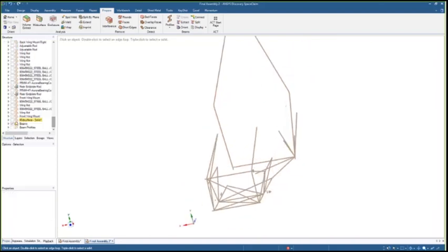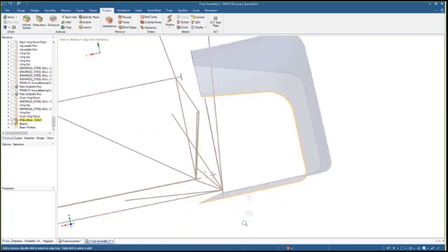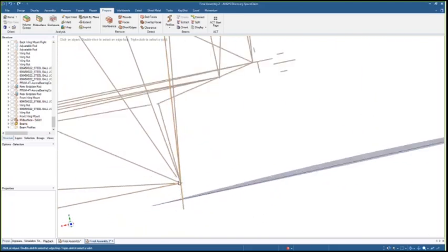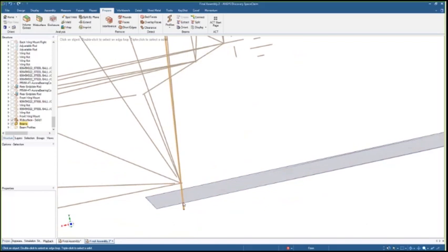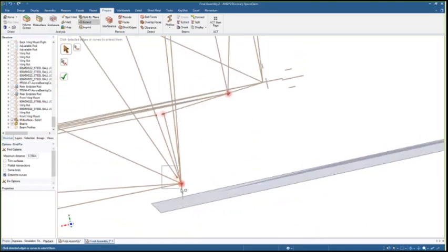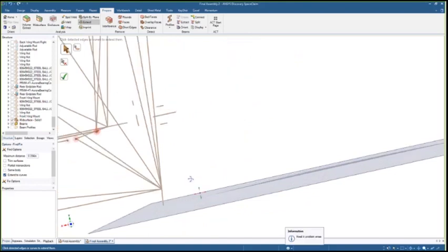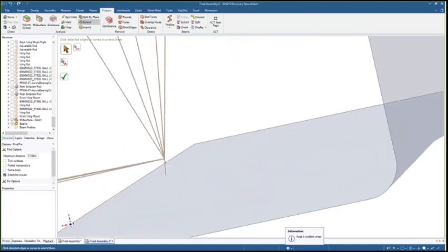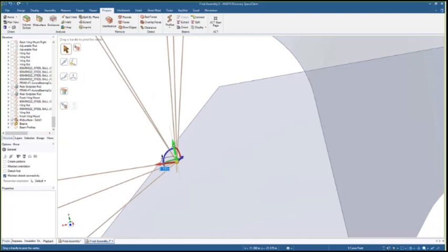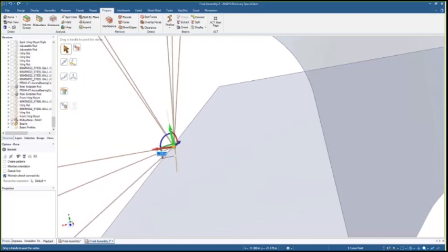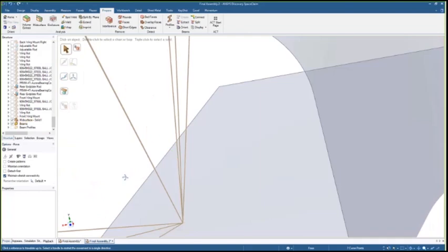And let's just go ahead and show that last mid-surface. So you'll notice that our beam elements are both not connected to each other and not connected to our shell element. But this extend operation does have that ability. Here, it trimmed it back to that surface, and now we could go ahead and extend these to one point. If there should be that connection like here, that's fine. Or, believe it or not, the move tool that I was showing before on solid bodies and surfaces can also work with beam elements. So if I just want to take those and grab that point, I could move it in 3 directions at a time right up to that point, and now we've got that connection.